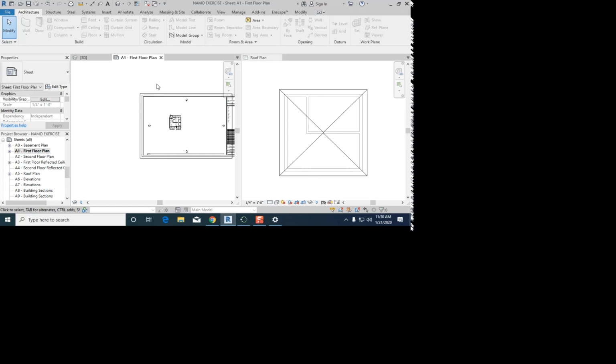Yeah, it references another level. So imagine we've drawn our first level and we go to draw our second. Our exterior core walls should keep going up, so we're going to see those. But if you want to align a staircase or plumbing, it helps to see the level below so you can really stack those walls on top of each other. So an underlay is just a visual reference for a floor below or even above. It's not common to do above, but typically it's just a reference level for you to sketch on top of.